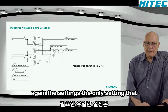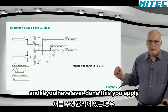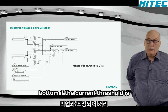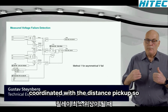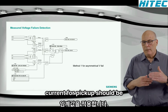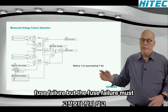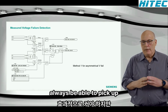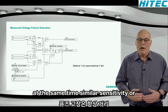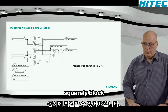Again, the only setting that you are required to make is the current setting. And if you have ever done this, you apply the current threshold at the bottom. The current threshold is coordinated with the distance pickup. So the distance relay minimum phase current for pickup should effectively be larger, not smaller, than the fuse failure threshold, because the fuse failure must always be able to pick up with similar or higher sensitivity than distance protection. So it will be able to securely block.